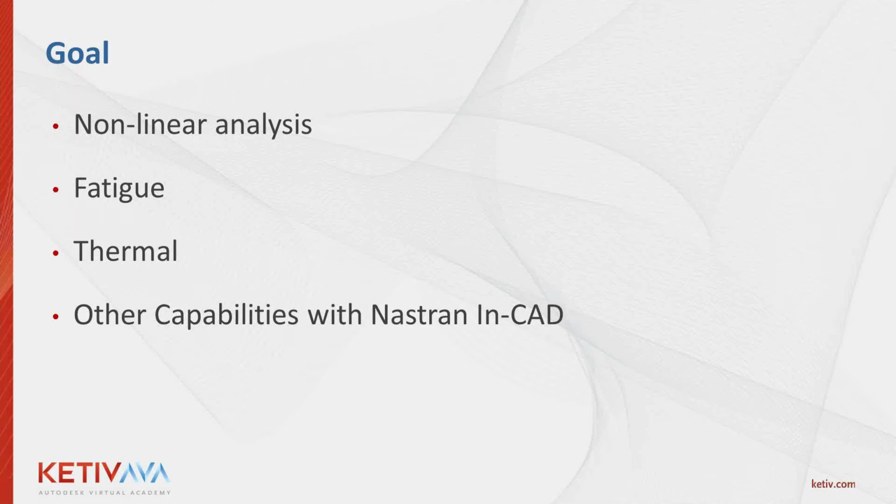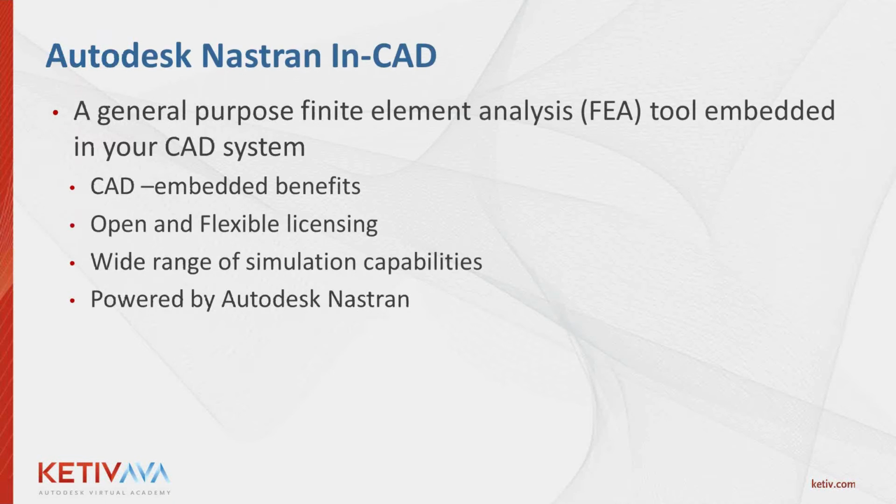And how we're doing all this is through Nastran In-CAD. I want to make clear this is a separate add-on to Inventor. It works inside of Inventor. It even works inside of SolidWorks in case you have other colleagues that want to use it too. Nastran In-CAD is an embedded tool inside of Inventor. It also has flexible licensing, with a network license. It adds more capabilities to what Inventor already has, and it also has some that Inventor already has as well. And it is powered by Nastran, which is a very well-known solver out there.